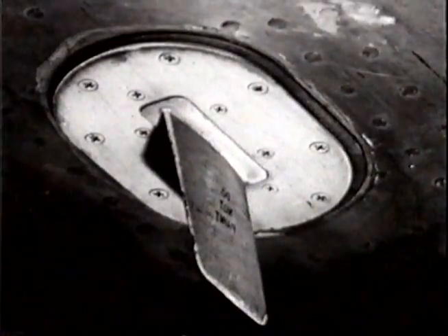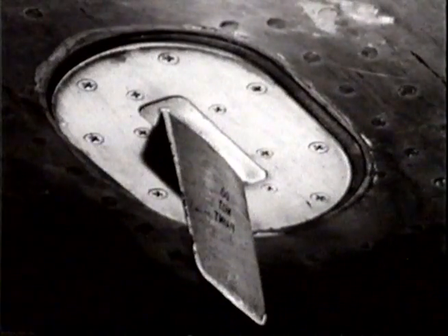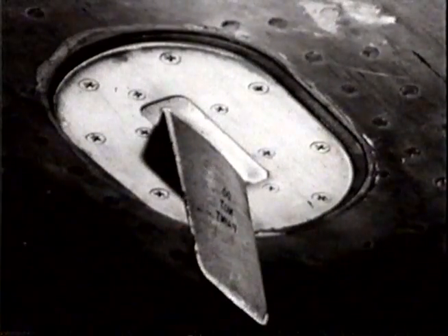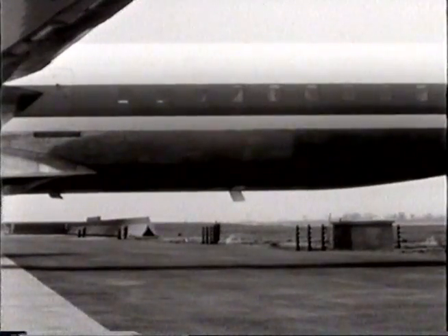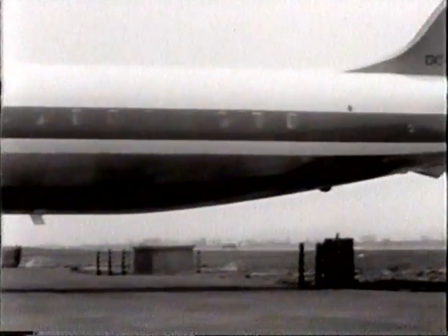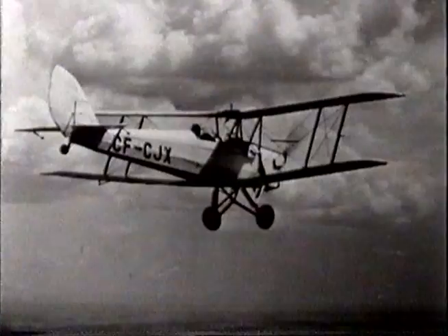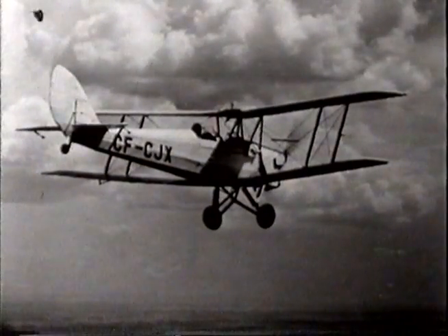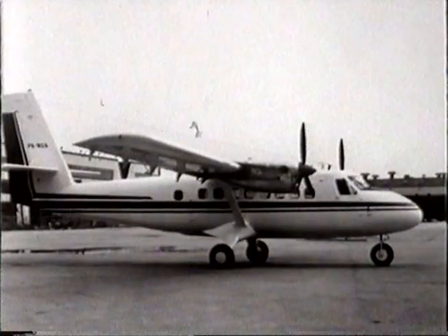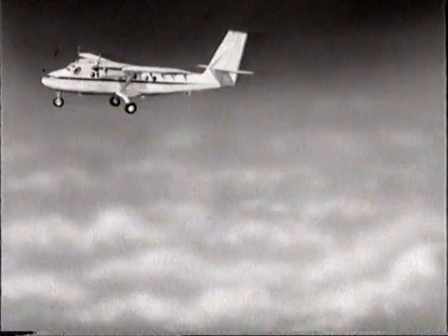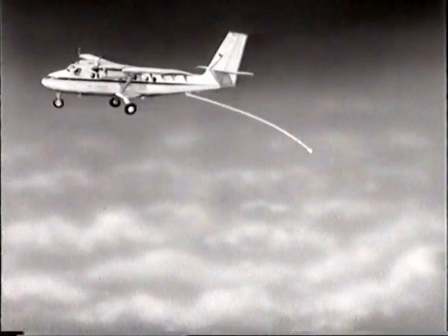This is a secondary radar antenna aligned with the primary radar antenna. In addition to extending and reinforcing the primary radar, the secondary radar can be made to receive and furnish identification and altitude information through the transmission of coded signals from aircraft in flight. This transponder antenna, located on the underside of the aircraft, sends out a return signal automatically when the beam from the primary radar antenna is being received.